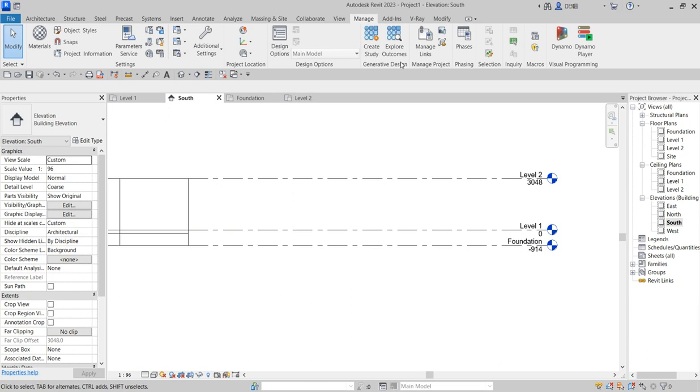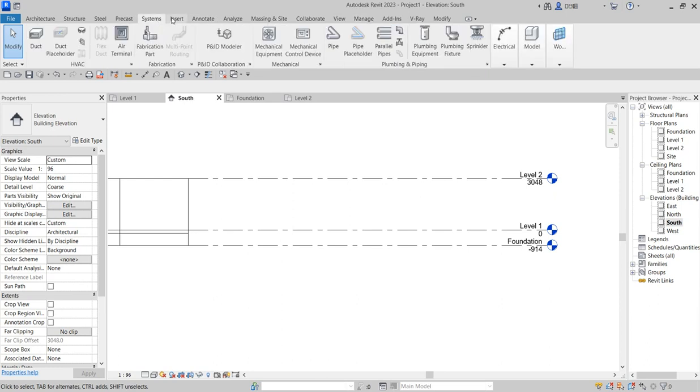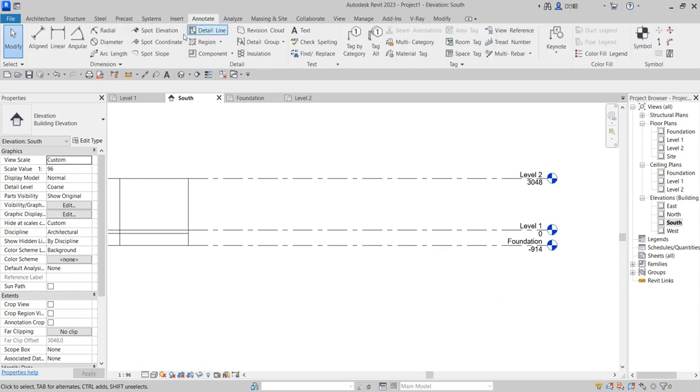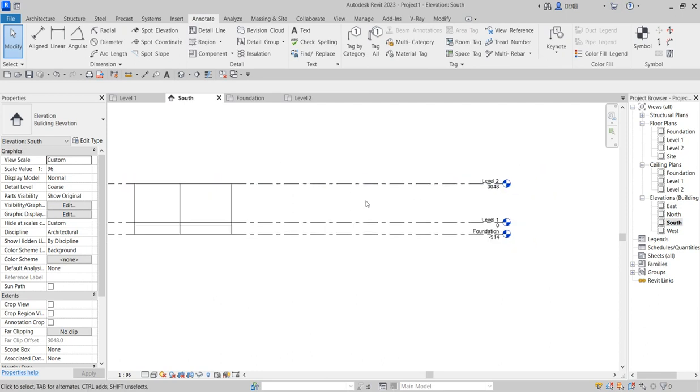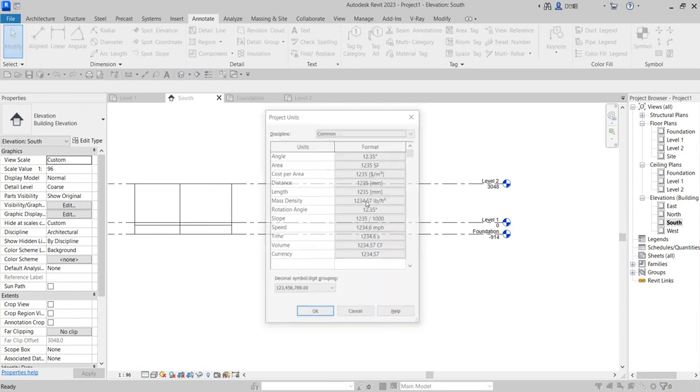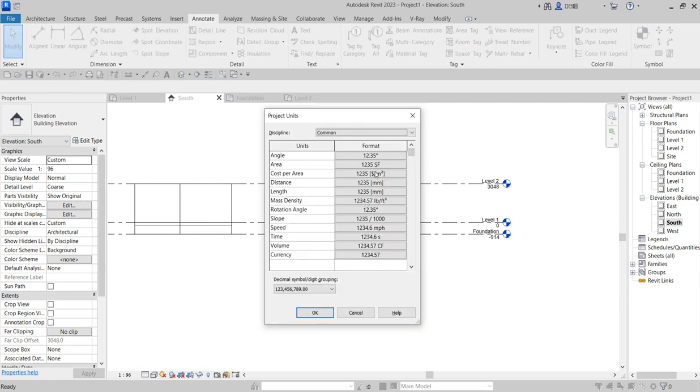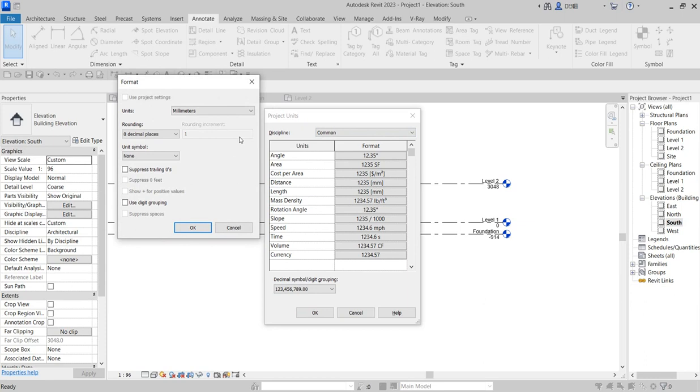I don't know, it should be somewhere here, but if you do not see it, that should not delay you, or worry your creative application part. What you just need to do is press UN on your keyboard and you change them back. Remember, UN, just press it, you don't need to press enter. This thing pops up, and you'll be able to change them back to feet. So we're using feet.